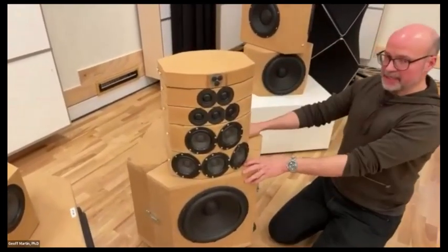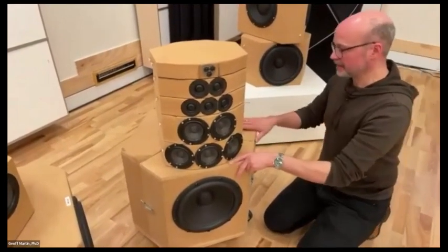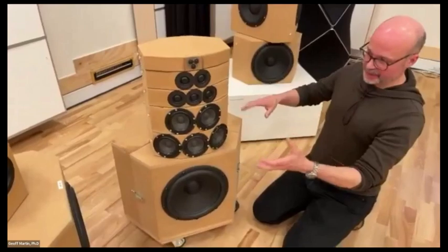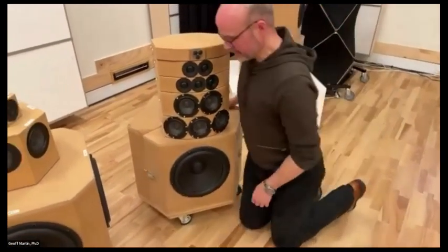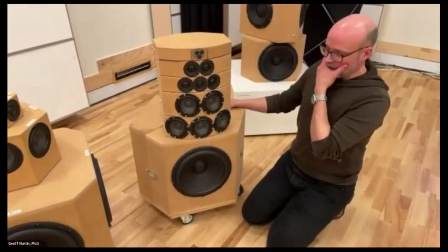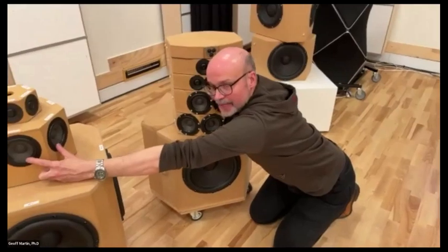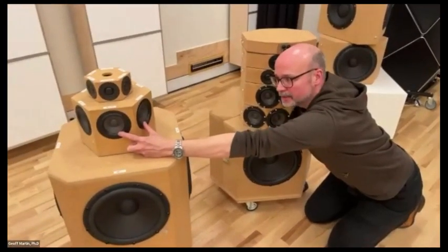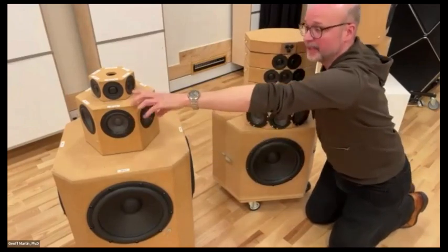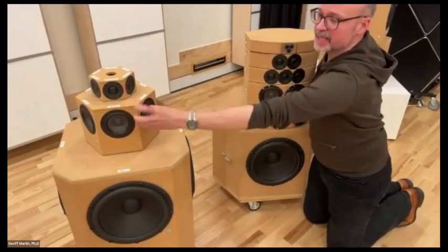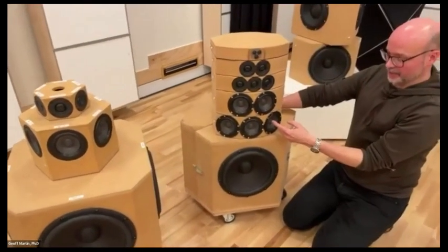Again, all of these are independent. Each has its own amplifier, its own DSP channel. Everything is completely separate. So it's not a 3-way speaker, it's a multi-way speaker because everything is behaving independently. As I said before, with the previous version, these 2 drivers are simply too far apart to reliably give us a narrow beam width. So we were getting lobing. So then the question was, how can we get these as close together as possible? And that got us to this solution.